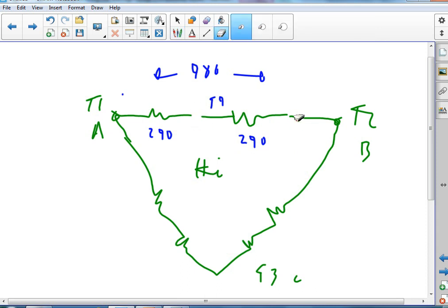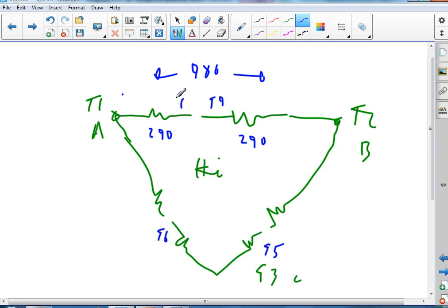So I'm going to break these windings there. So T1, T4, T5, T6, T7, T8, T9. And so now I can run it through a bunch of contactors and start it as a Y connected motor, and when it gets close to that speed, have it 2 seconds later or whatever, I can shift it to a delta wound motor and run it that way, just to be more efficient.